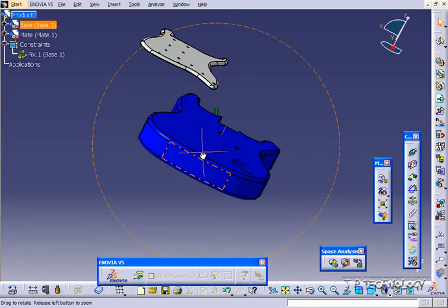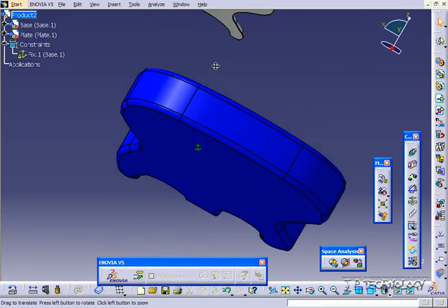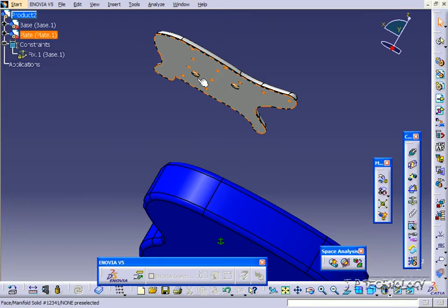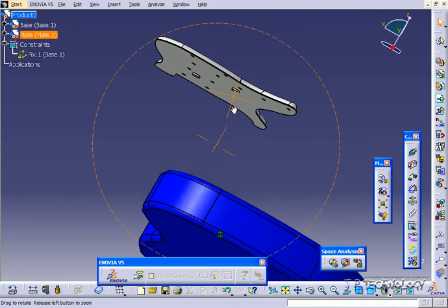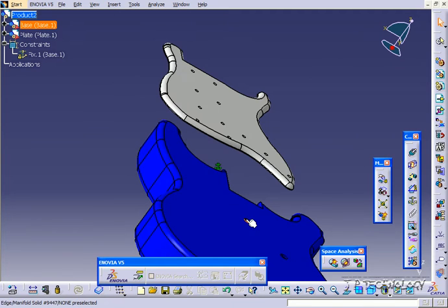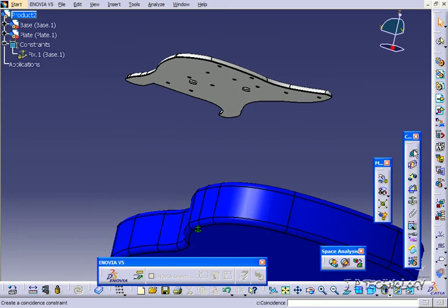So what we need to do is, I've created a few pilot extrudes here. So these extruded circles are going to have to go into these cutout circles, and then we're going to have to create a coincident constraint between these two extrudes and circles, and then we have to make a contact constraint between the two faces. So let's start off with the circles. Let's click coincident constraint,